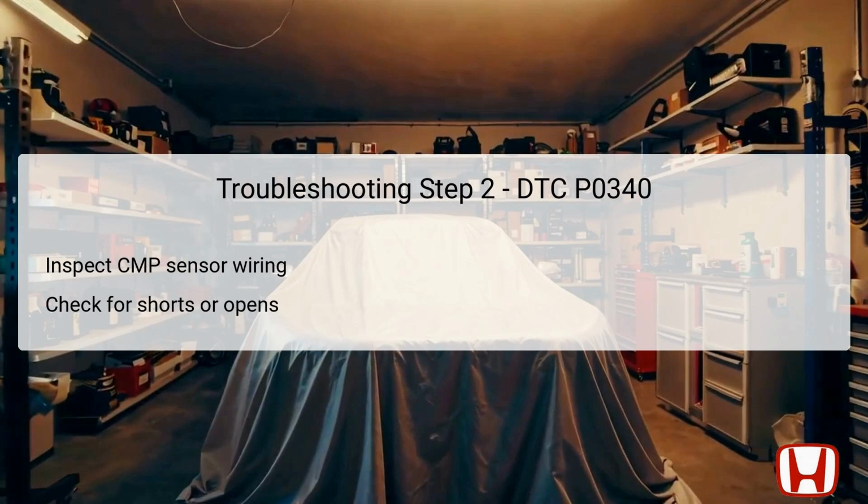This inspection typically involves visual checks as well as electrical tests with a multimeter to confirm continuity. Ensuring the integrity of the wiring harness, connectors, and terminals will eliminate potential external factors that could lead to the malfunctions noted in the DTC P0340. Adequate attention to these details is critical in isolating the issue.